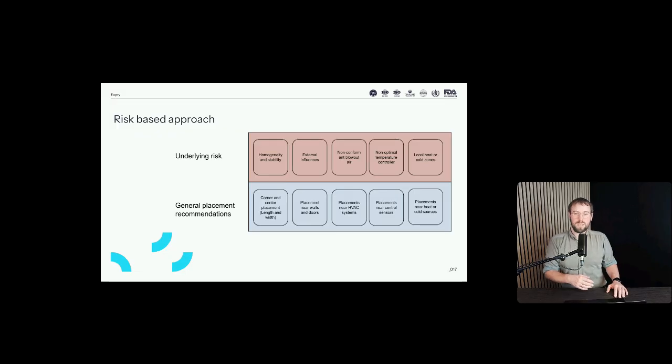And therefore, it's really a matter of placing temperature sensors where we'll get the first indication that temperatures are outside acceptable ranges. So another output we often get is that we find, okay, during a power failure study, which area is affected first? So let's say you do have a power failure, and the spot that we found out during the mapping study is the one that gets hottest first. If that is within limits when we restore power to the system, well, then we can reasonably say that all other temperatures also should be within those limits. So we avoid a lot of having to deal with nonconformities or incidents and throw away product.